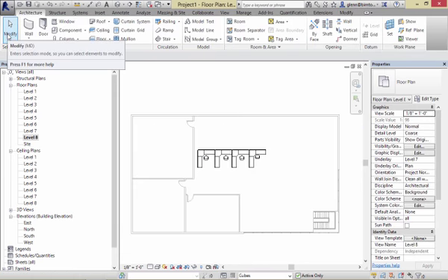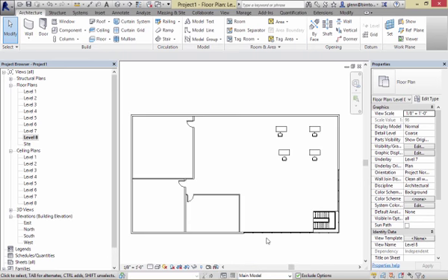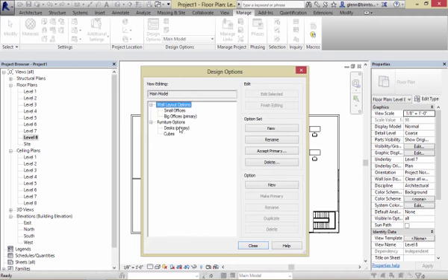Okay, zoom out. This is my cubes option. If I go back to main model, what's going to show up? Desks or cubes? Desks. Okay, it's primary. If I switch over and I want to have the cubes become the winning option, it'll be Manage, Design Options. I'll make that primary. Okay.